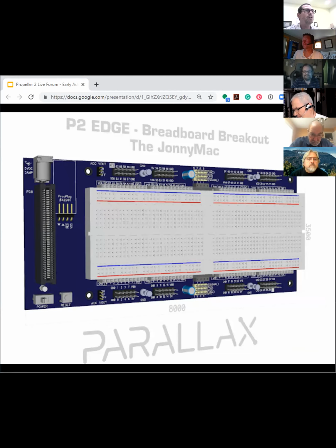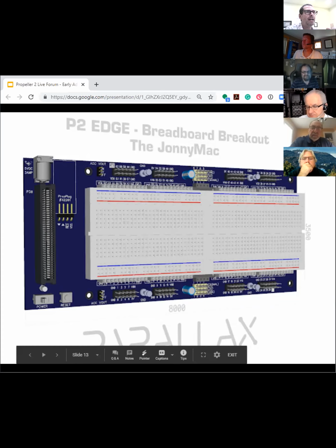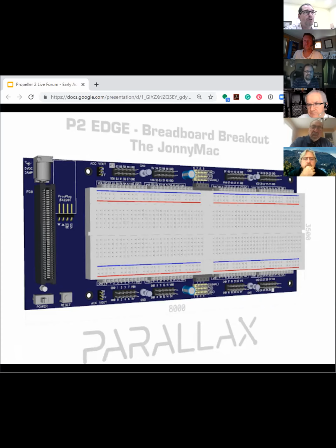So what we could do is put some of those on the board and actually make it selectable. So you could route those pins that would otherwise be going to the HyperRAMs down to the edge fingers on the card, which is kind of cool. I mean, it wouldn't impede the path very much, and it would allow you to use one, none, or both of the HyperRAMs and get the pins back on the connector. But otherwise, if you're connected to the HyperRAM, those pins will be high impedance on the edge fingers.